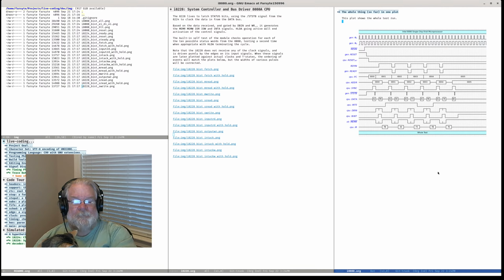So my plan is to grab a couple of I/O ports, and I will probably grab the same port numbers that are used by one of the existing systems. And instead of emulating the chip itself, I'll just say, when you read from this port, we're going to tell you whether there's data available and whether you can safely send data.